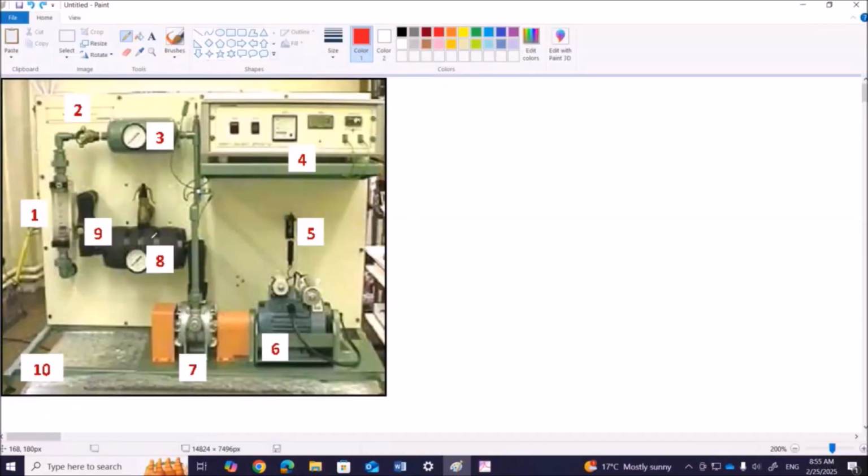First, I will explain each and every component of the thermodynamic system. The compressor. This is the electric motor which is used to run this compressor. This compressor is a vane type of compressor. We have two types of compressor, reciprocating and rotary, and this comes under rotary. It is not a reciprocating compressor. This is the inlet. The inlet air comes in and the outlet air goes out with high pressure energy. That's why it is insulated, because it is high pressure and high temperature.